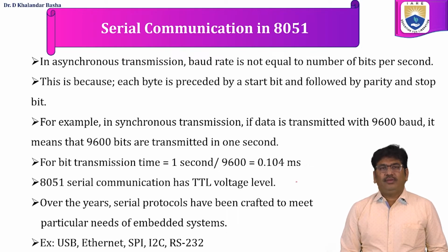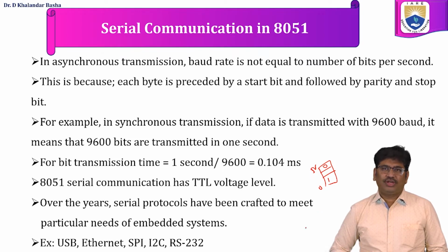In 8051, the serial communication has TTL logic levels, where the voltage levels for logic 1 and logic 0 are defined based upon the TTL logic family. Over the years, serial protocols have been crafted to meet particular needs of embedded systems. Examples are USB protocol, Ethernet protocol, SPI, I2C, RS-232.